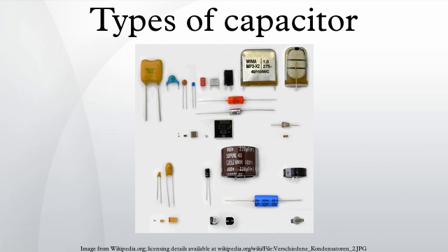Although electrolytics' leakage current is higher than current flow over insulation resistance in ceramic or film capacitors, the self-discharge of modern non-solid electrolytic capacitors takes several weeks. A particular problem with electrolytic capacitors is storage time. Higher leakage current can be the result of longer storage times. These behaviors are limited to electrolytes with a high percentage of water. Organic solvents such as GBL do not have high leakage with longer storage times. Leakage current is normally measured 2 or 5 minutes after applying rated voltage.